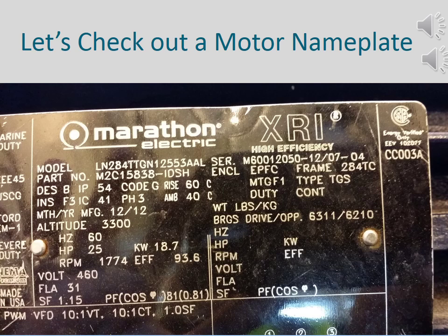The nameplate also has the motor's full load efficiency, or EFF. If we are dealing with a newer plant, we probably have the newer energy-efficient motors already in place, so it is likely we will find our only ECM opportunity will involve the way we operate that equipment to save energy. If we have older motors around, a desktop evaluation, like this, is an excellent way to evaluate those motors. Most of the newer motors today are already very efficient because of the new electrical standards.